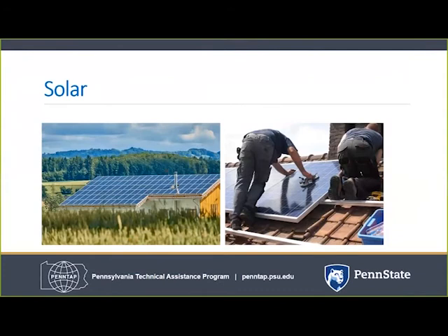Solar energy installations are likely what you see most often. The equipment is easy to recognize and often installed in a prominent location. This visibility is a selling point for businesses that want to put their commitment to renewable energy on display. Its value as an energy asset does depend on local weather patterns and the sun exposure available at your site. If you are unable to use your rooftop, you will need open land. A location with southern exposure provides the most direct alignment with the course of the sun across the sky. Within Pennsylvania, the south and east generally get the most sun compared to other regions.